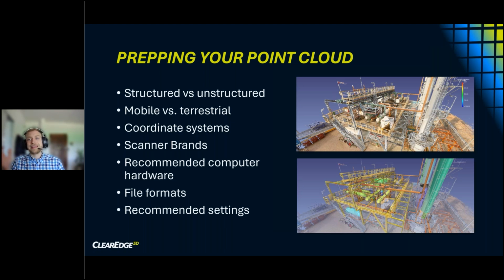So in general, it's pretty straightforward with EdgeWise specifically. You will figure out the coordinate systems that you're agreeing on for your project, for your client. And that would be what you're bringing into Revit or AutoCAD, like where does that need to be? That needs to be pre-decided.